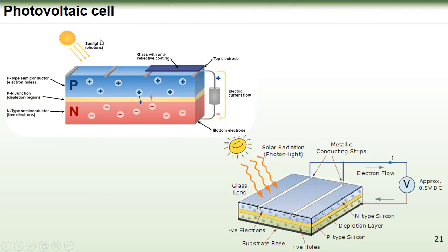Now the backbone of PV systems is the solar cell or PV cell. In a typical solar cell of silicon material, two layers of silicon are present. The first layer is silicon doped with phosphorus, and therefore it has extra electrons to share, and the other is silicon doped with boron, and therefore it has extra holes to share. When the sunlight hits the solar cell, the electrons migrate through the p-n junction, and a potential difference across the cell is presented. For a typical silicon cell, it's around half a volt, and current can go through the external circuit carried by the connection strips, commercially known as busbars.